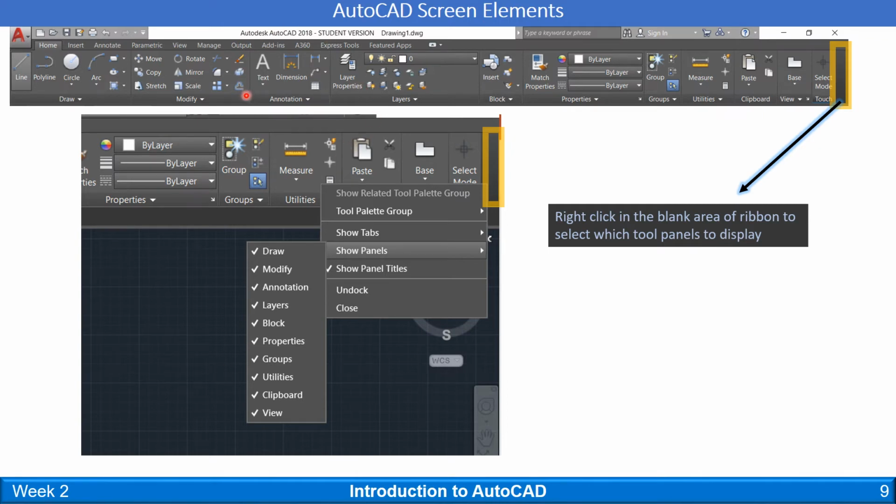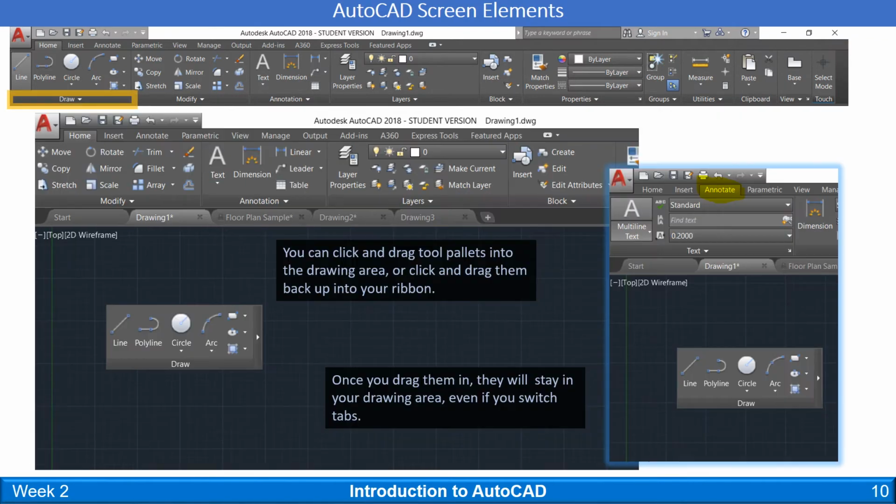If something isn't showing up, if you see buttons in this presentation that are not going on your screen, this is how you get them. You just right click on the edge and then make sure you have everything checked for what you're trying to use over here. Okay, so here's another cool little trick that you can do. You can take tools out of your ribbon and you can click on them and actually drag them into your drawing area. And you just grab it right here at the bottom, somewhere in the gray area, and left click and hold that clicker down and just drag it inside.